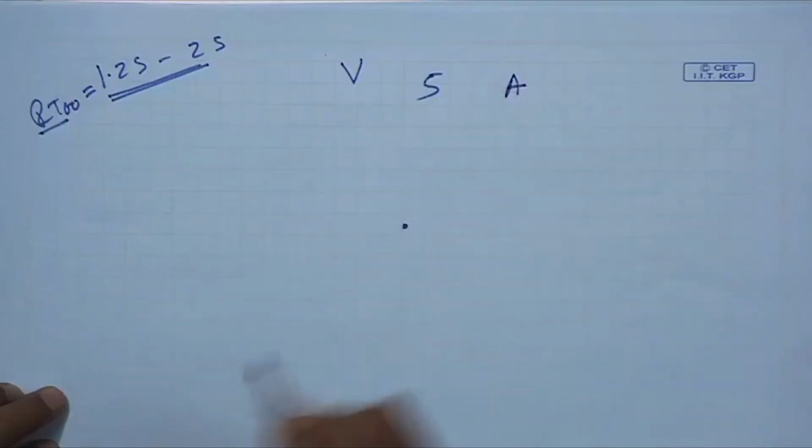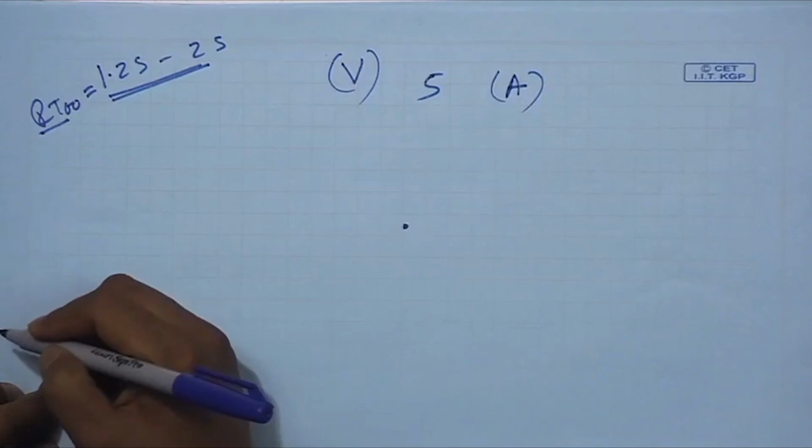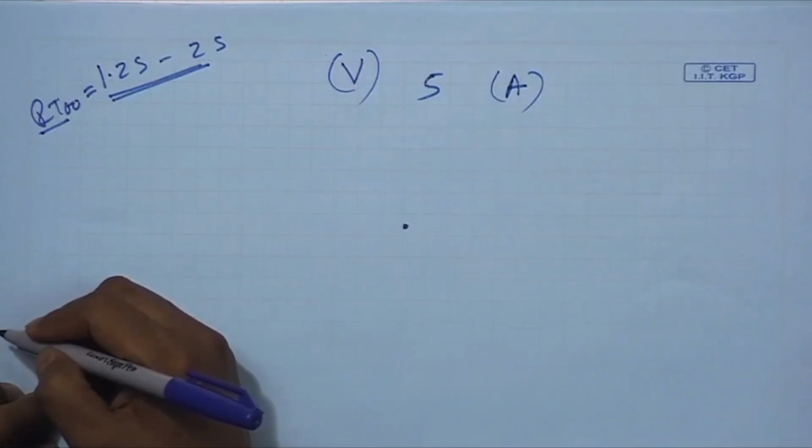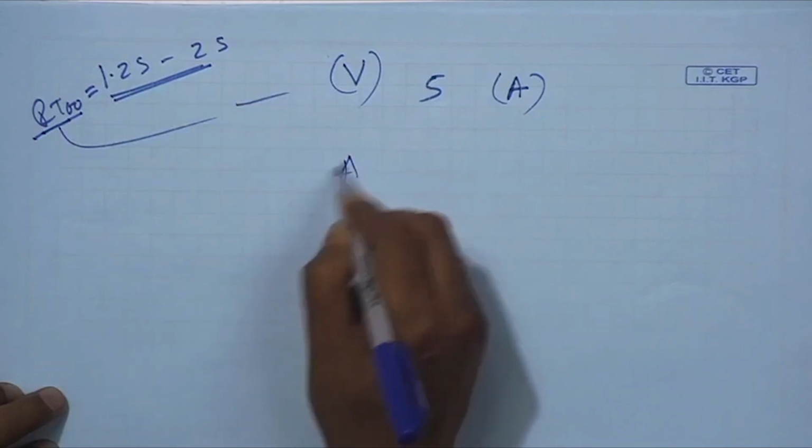Everything's absorptivity is given and their surface area is given. Then I can calculate capital A, the average total absorptivity of the whole surface area. Once I know A, I know V and RT60, I can estimate what kind of A I require.